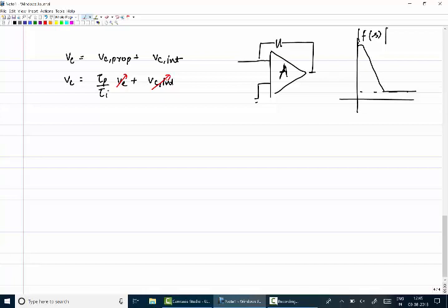But if I give a small step itself, then the phase error may not saturate and the feedback part works to bring the integral part to the desired value. Okay, this is a little bit of a thought process. When you try to do it in simulation, you will observe this. Phase error saturates due to the properties of the mixer. Yeah, the phase error detector is a mixer.